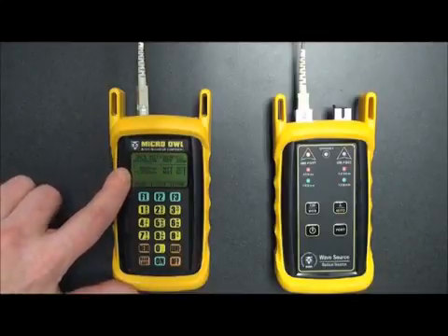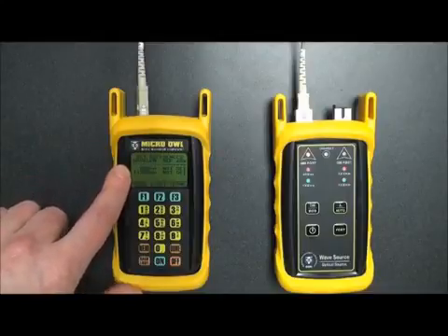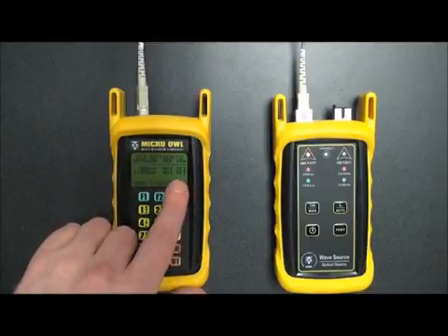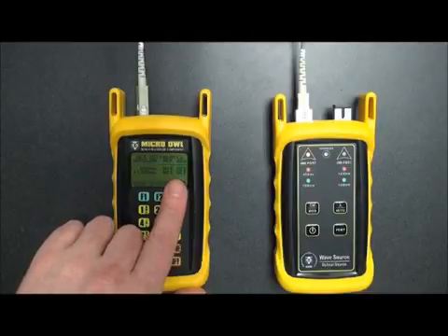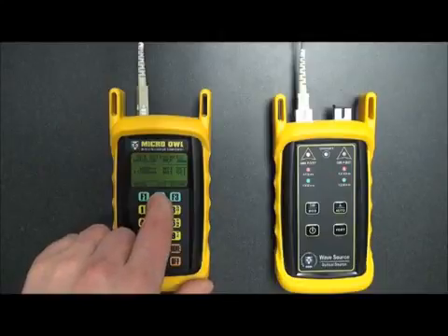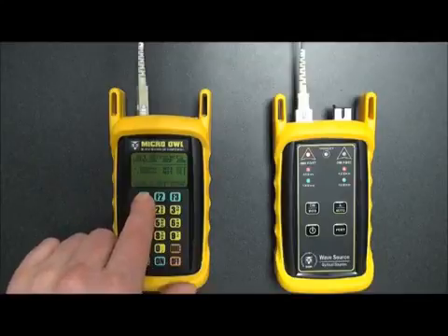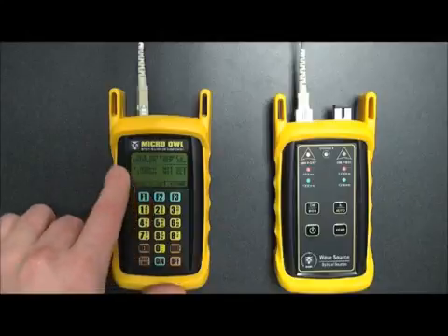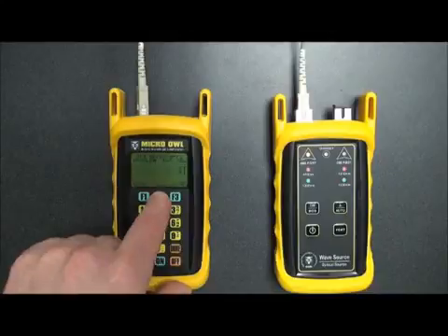On the left-hand side, you can see an asterisk. That simply denotes which wavelength is currently selected. And then over on the right-hand side, you see the reference level in dBm. Now you can see it says not set. It's because we haven't set the references yet. Now, in order to set the references, we will press the F2 key here to start the set reference procedure. But what we want to do first, let's go in order here and start with the 850 nanometer wavelength. So once we have our wavelength selected, we press F2 to begin the set reference procedure.